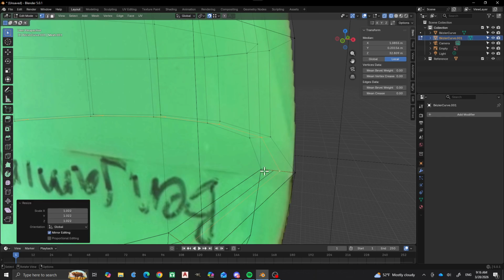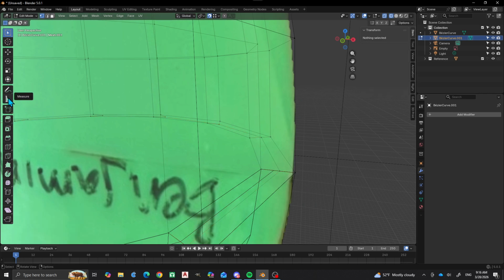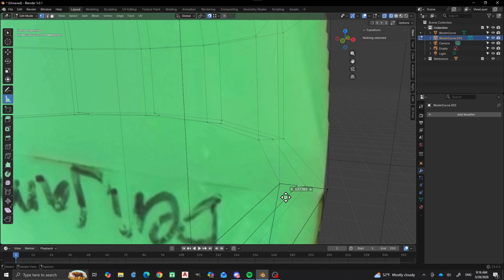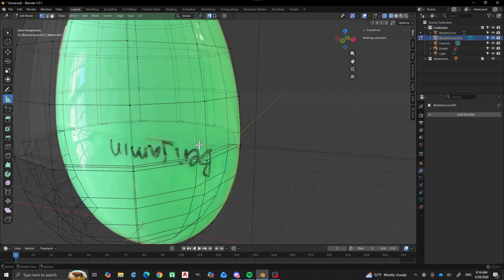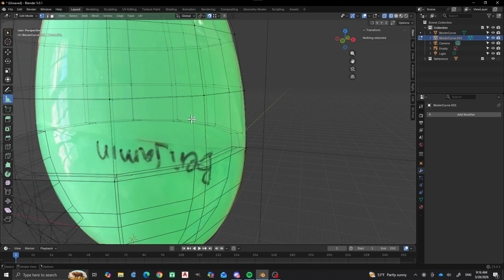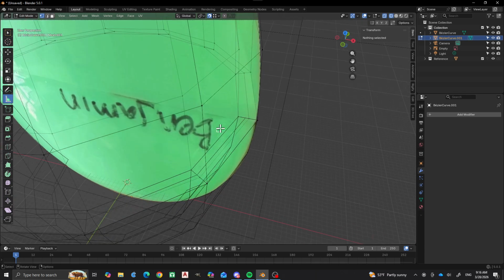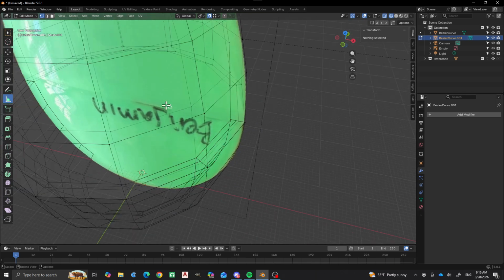So what I want to do is I want to have a gap between these two right here. Okay, so I'm going to do another measurement right there. Okay, 0.5. Okay, so 0.5. That's a pretty decent sized gap. That might be a little too big. So actually, that might be exactly what we're looking for, because I have done tighter gaps and they've typically been really hard to get apart if I want them to actually come apart. Okay.